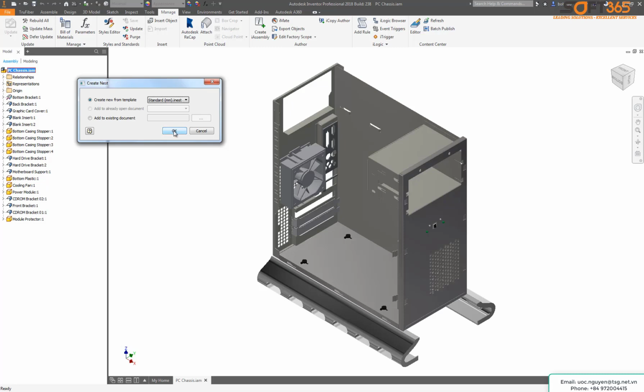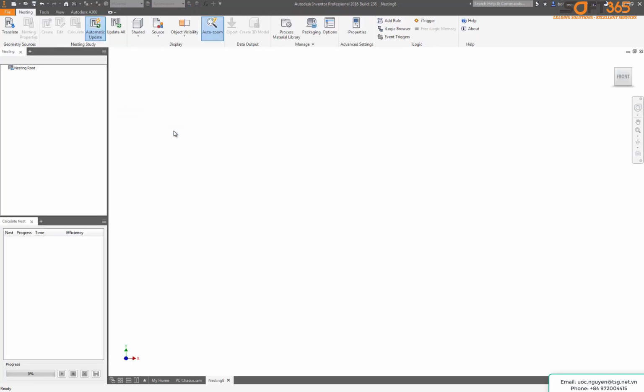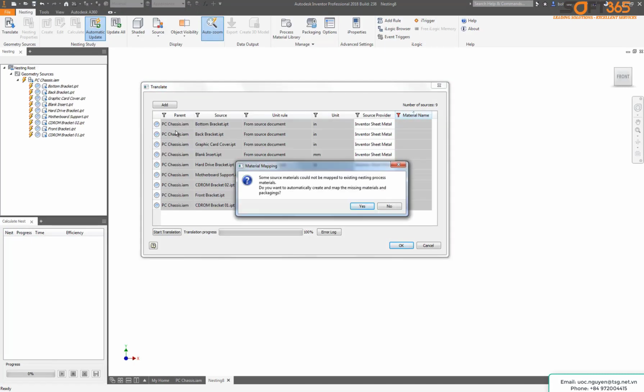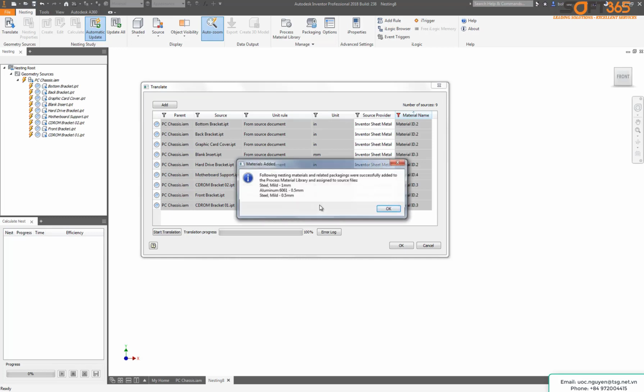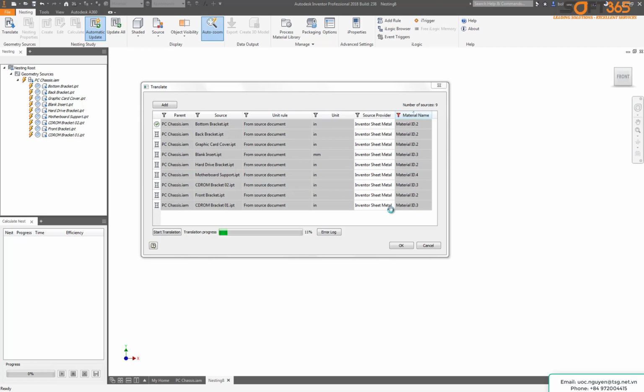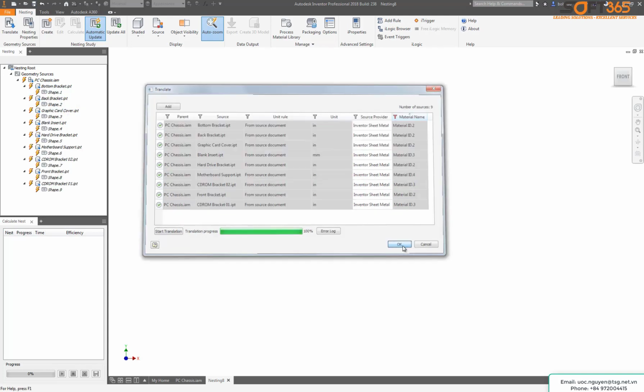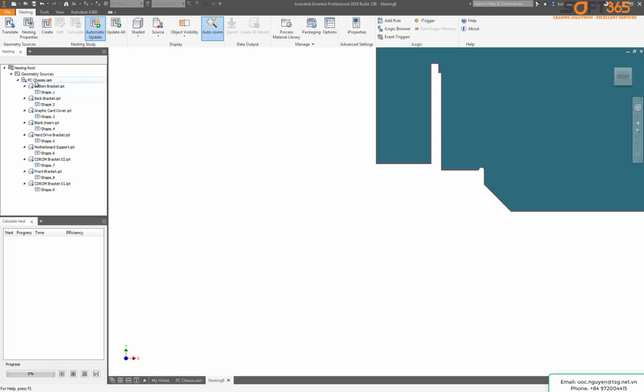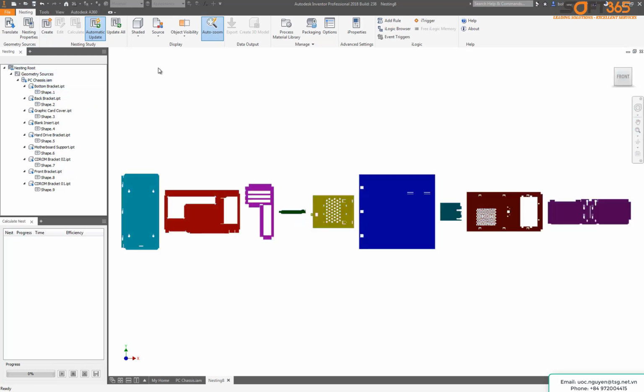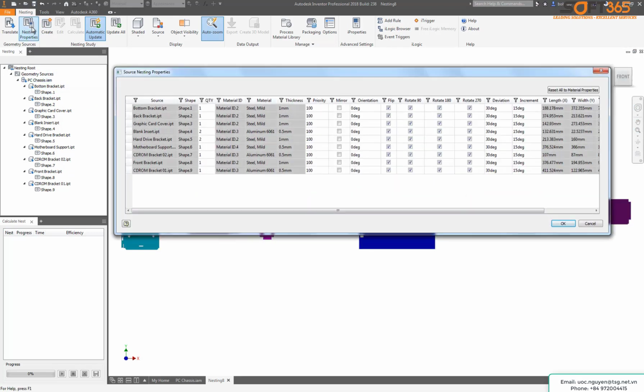and on open we immediately detect only the sheet metal files. We see that there are 3 different materials with different thicknesses. At this point we're reading in the closed loops from those sheet metal flats, and you see on the left in the browser the shapes materializing. Each part is colored differently here. Just to prove that we are able to read in the bill of material quantity correctly, you see the 2's